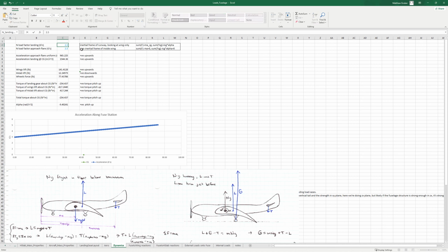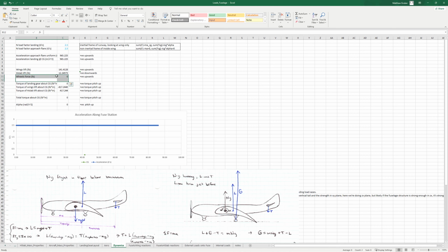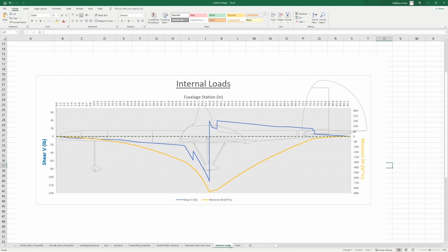Then we would be sure that the wheels are not getting involved at all, but the aircraft is pulling that maneuver. And we could look back here and see what the loads diagram looks like. So each of those individual ones, we'd have an output for these loads diagrams. And as far as what we design the structure to, we have to make it strong enough for any one of those maneuvers to be happening to it.